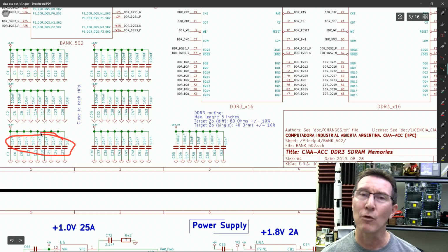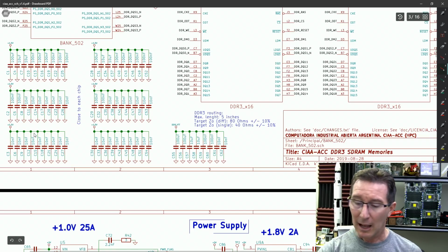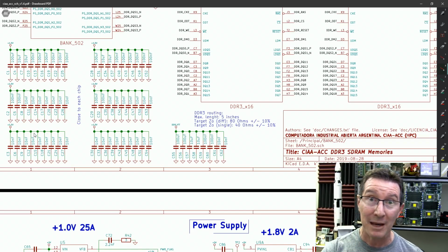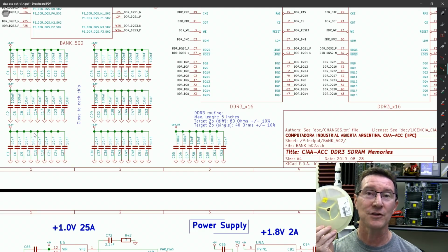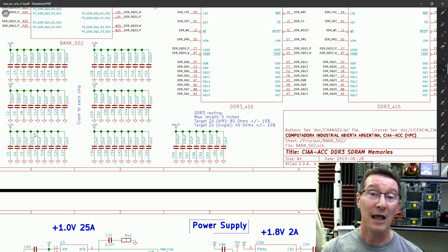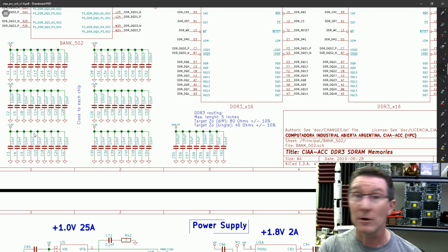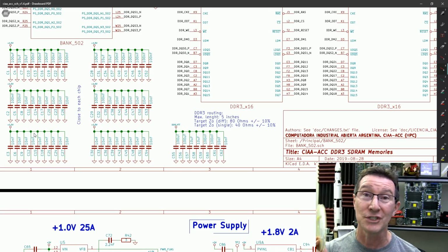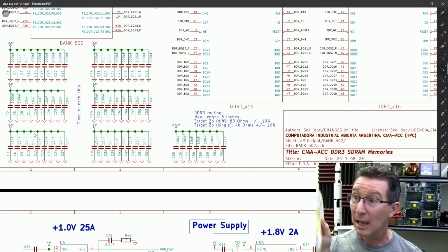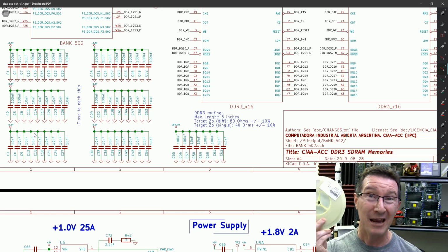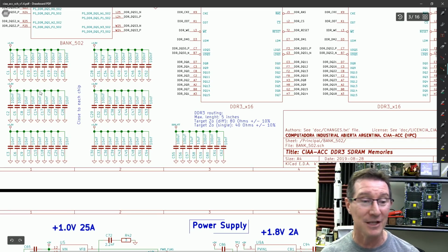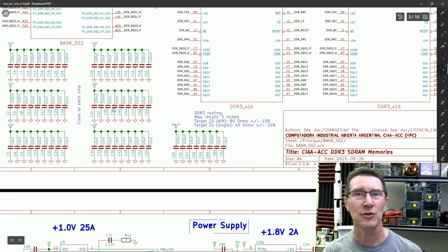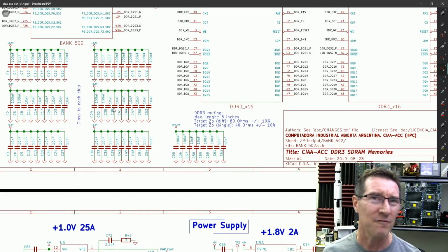So while they're all the same values, even if you use too many capacitors, even though you might have 4,000 on a reel, you're manufacturing a lot of boards per hour, your reels can run out earlier, and then a red light flashes on top of the machine. Quick, the whole production line is stopped because you ran out of your 10 nanofarad capacitors because you used 10 gazillion of them on your machines. Somebody's got to come around and replace the reel and start up the line again. And they cost money, especially if you're using the more expensive 1 mic and 10 microfarad ones.